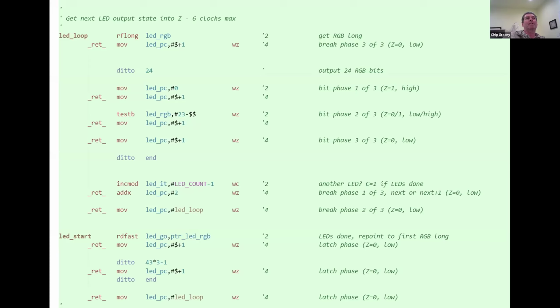They would certainly start a conductive path to ground, and take some of the burden off of the TVSs and things. A circuit board version is definitely a lot cheaper, and I can imagine it working just as well. I should have pulled a picture up of that. They're just little fingers that come together like this. The only question is how to clear out the carbon after it does track.